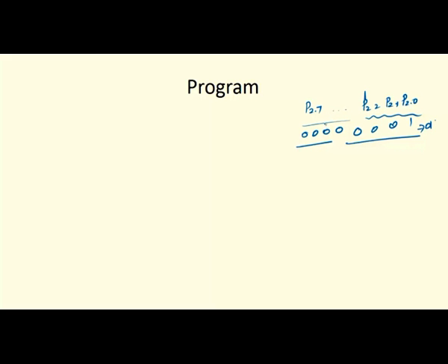So, by using port 2, MOV P2, #01H. Only 3 bit positions we are using to select the particular channel, the remaining are not used, right. Then one more instruction we have to give, P0, which is for the digital output. I will initialize it as 00. This one is initialized for the digital output, and the other is for channel selection.